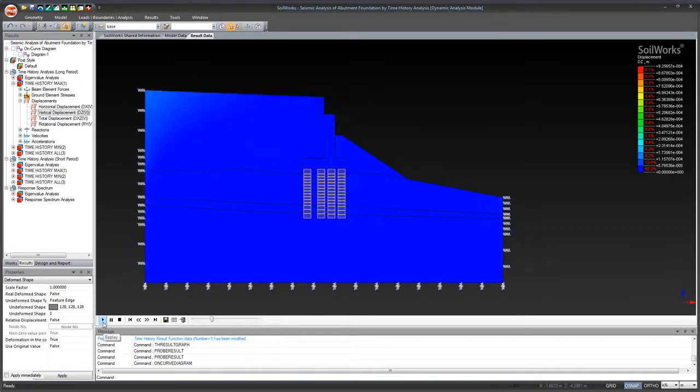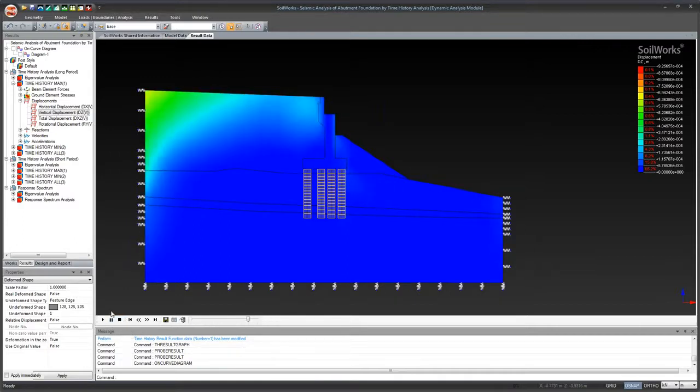And what you can do is press play here. Okay, so look how it goes back and forth. This is from the very beginning to the end of the earthquake. Naturally, the part that we showed initially was the maximum. But if for whatever reason you want to see how it gets to that point, or how the model changes up to that point, just click play here, and you can see very slowly how the contour diagram shifts along each point of the earthquake.